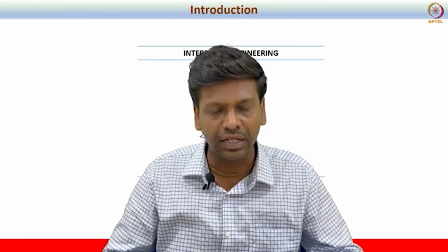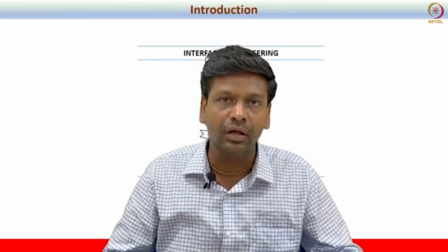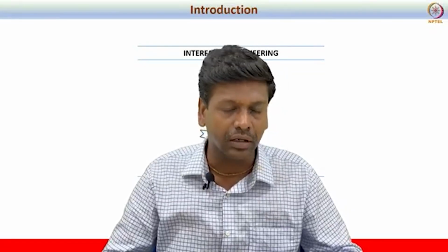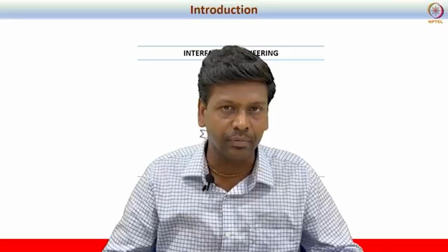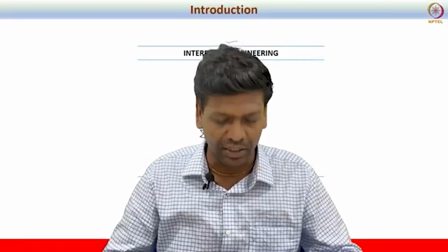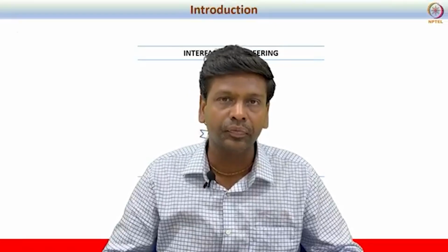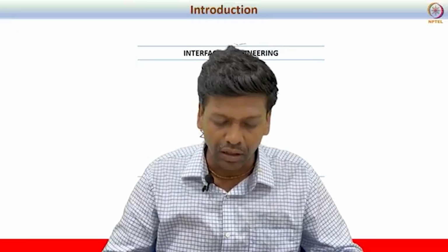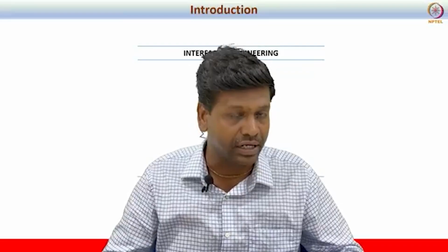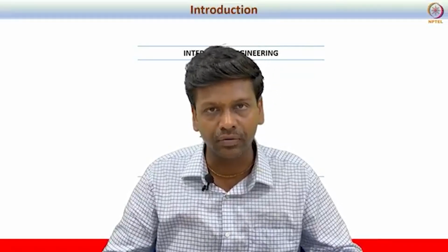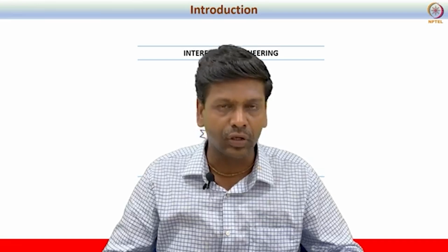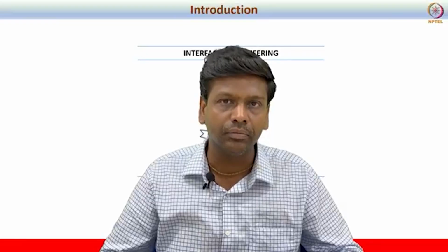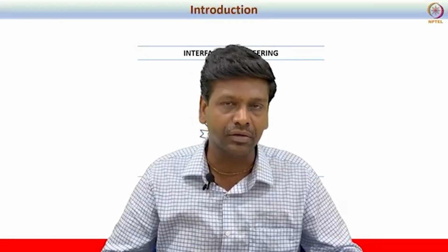But in today's video lecture, we will look at the Young-Laplace equation, right? And we will look at how the governing equation can be obtained. So in general, the Young-Laplace equation is used to understand or predict the equilibrium shape of curvature, right? We know that whenever we consider curvature, there will be a pressure difference across the interface, right?